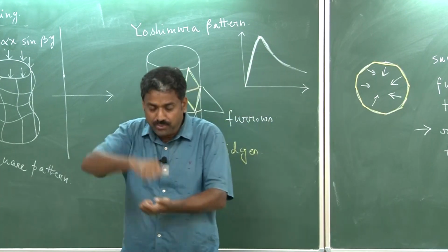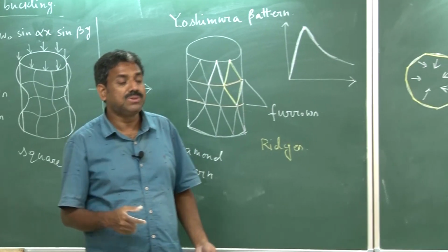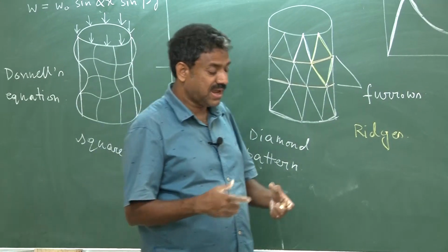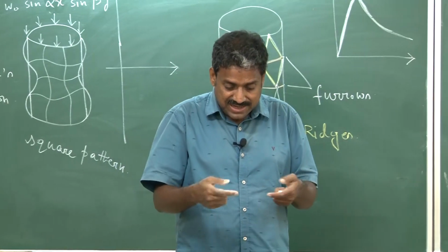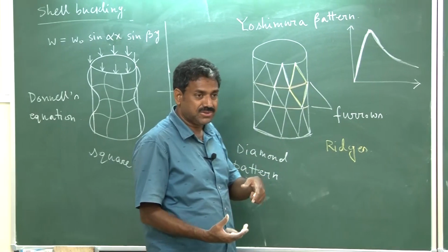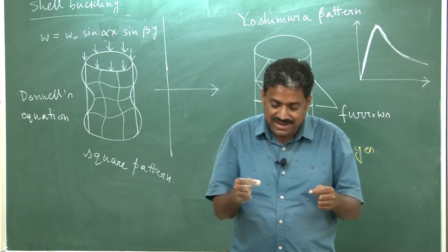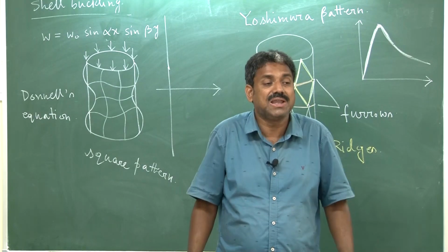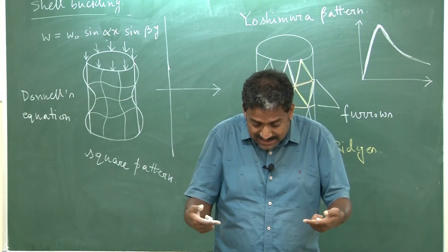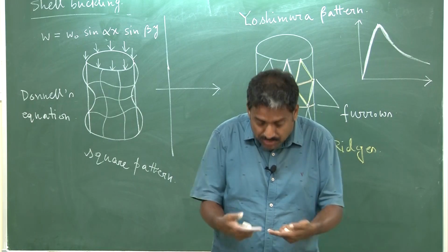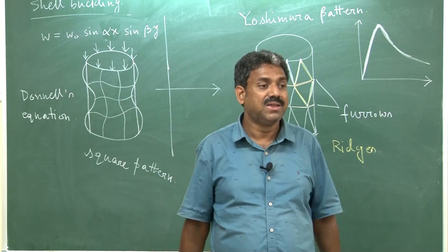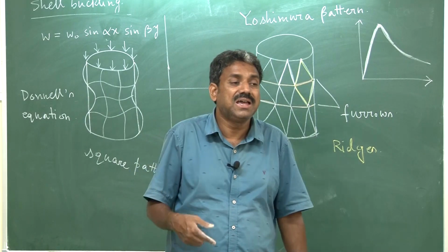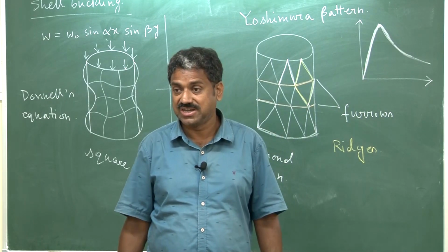And when you push a cell, you can do this experiment, you take either a Coca-Cola can or a beer can, and then you push it. You will not get this UFO pattern because you do not have a mandrel-like arrangement, but you can definitely see that at the middle there is a concentration, a localization of displacement happening, and there is a tendency for it to propagate or move inward, so that it takes essentially the bending strain energy instead of membrane strain energy. Okay.